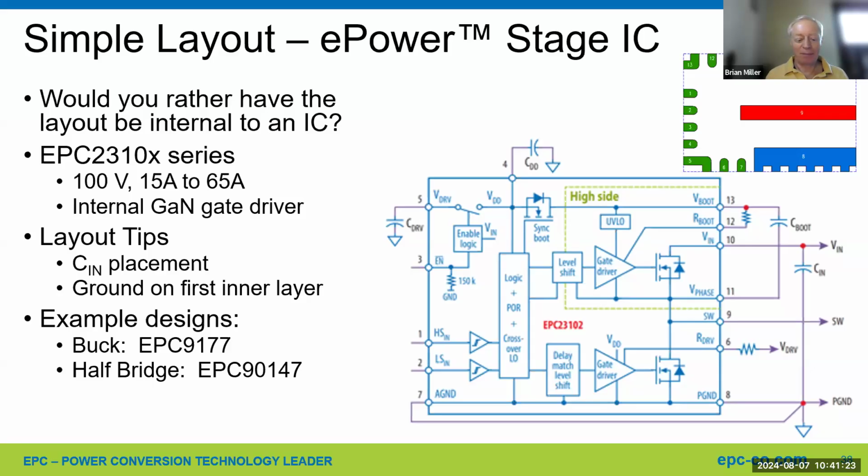If you're asking about, gosh, a Schottky at 400 volts is pretty bad, or some other diode is pretty bad, I think it's okay, and it doesn't need to be very high speed either. There's capacitors there. So as long as you're not trying to switch very high frequency, like over megahertz at very high voltage, I don't think it's all that critical. One where it is critical is for a TI 200 volt gate driver, but they have excellent documentation in their data sheet as far as the recommended part for that one.